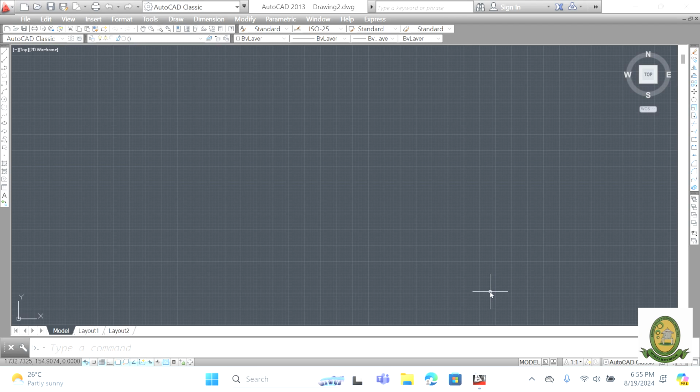Before we do any work: when starting a new drawing, AutoCAD uses templates to set up basic units and settings. That's why we've picked one of the templates there, which I told you is a CAD-ISO, named plot. You can customize this later, but for now, we stick to the default settings that are provided there.